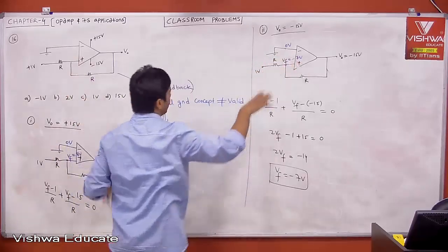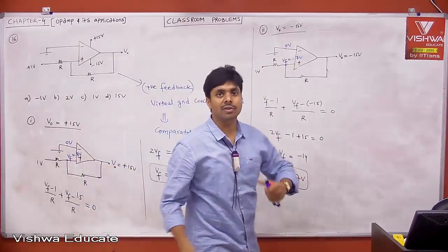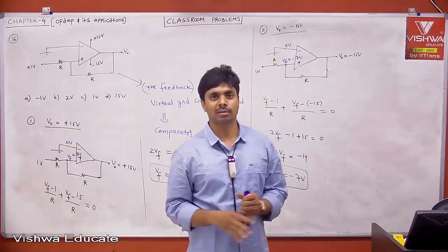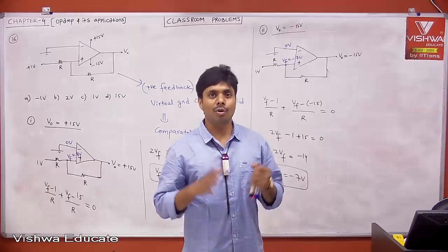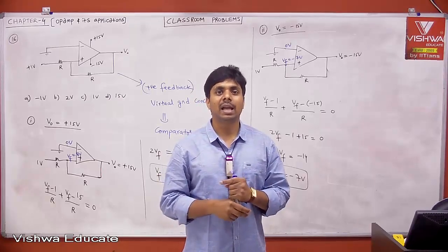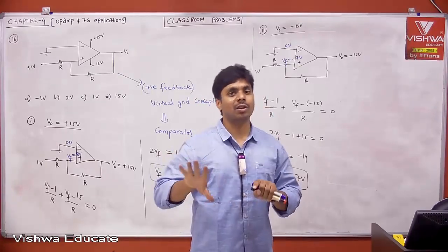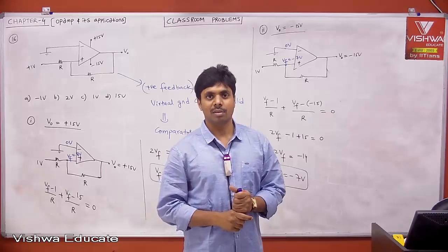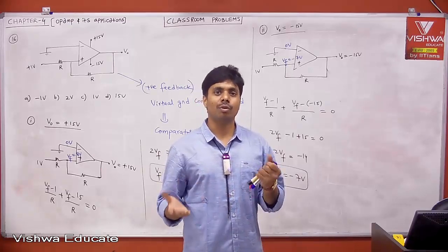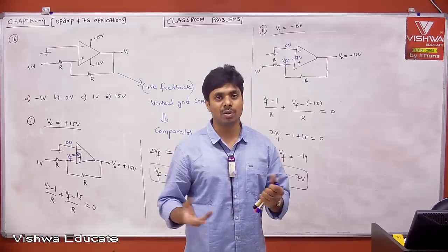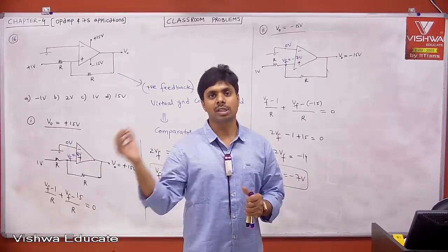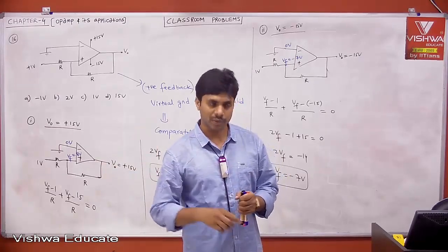At the inverting terminal, it will not change the state of your output circuit. It will stay there only. Okay, that is what is called bistable element. Therefore, both the states are stable until you apply an external trigger. We cannot change the state of the circuit. But if you take astable, there both the states are not stable. Continuously it switches from one state to another. That is what your square wave generator is, which we will see in the next session. Okay, take this problem.